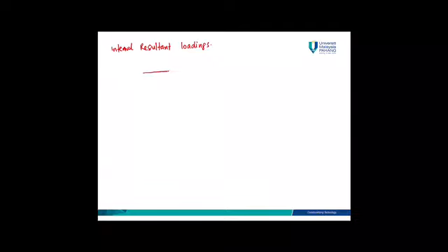So draw again the free body diagrams. Put the value. AY is 20 kilonewton. BY should be downwards, which is 10 kilonewton. And the applied load is 10 kilonewton. This is your point C. You need to cut at point C.